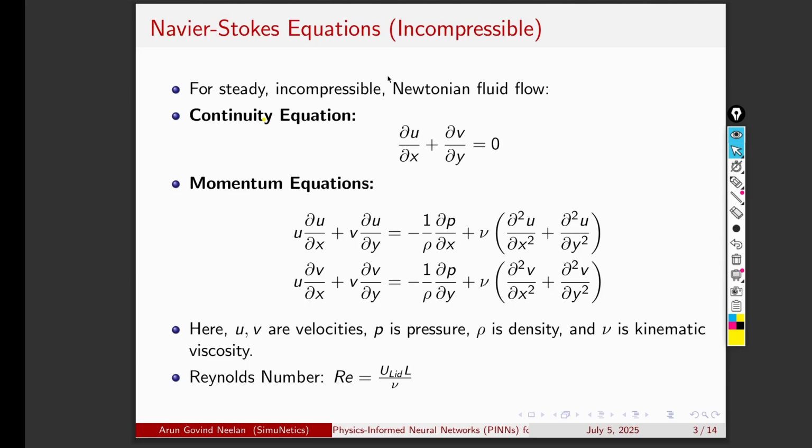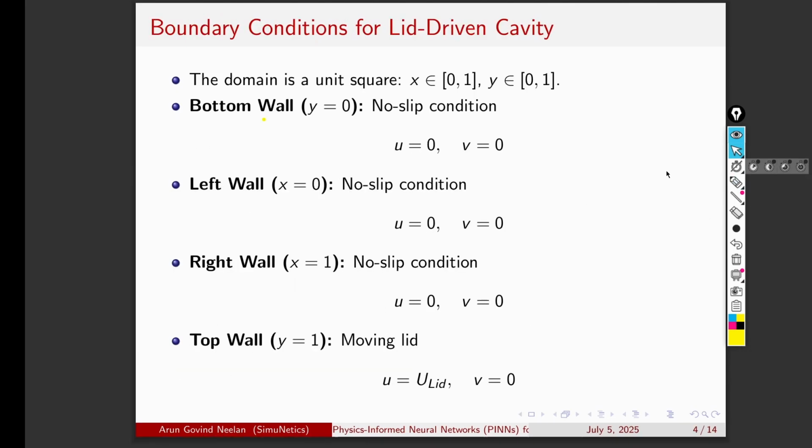So of course, for this problem, our governing equations are the continuity equation and the momentum equation. These are the boundary conditions. In the lid-driven cavity, I hope everybody is familiar with it. For the sake of time, I will briefly explain the test case. A lid-driven cavity has fluid inside a cavity. The only difference is the lid at the top will be moving at one particular velocity, moving like this, and we'll have fluid here. Because of the shear, we'll be getting a lot of vortices inside the cavity. So this is the problem we'll be solving.